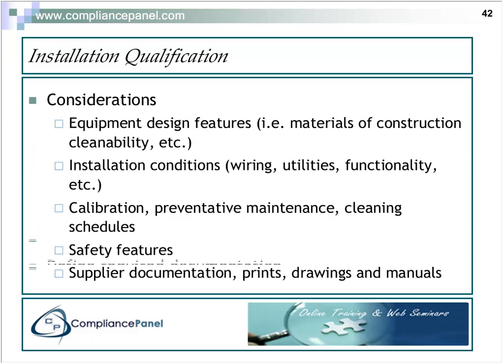We need to understand the equipment design features, how it's constructed and how it's cleaned, what kind of installation conditions apply here, the wiring, utilities, functionality, and so on. Any calibration that's required, any preventive maintenance required, cleaning schedule required, and we need to set all those up in this phase so that we have the proper maintenance, cleaning, and so on. Any safety features that prevent the operator from being injured, for instance. And the documentation, prints, drawings, and manuals that accompany it need to be available to people performing IQ.